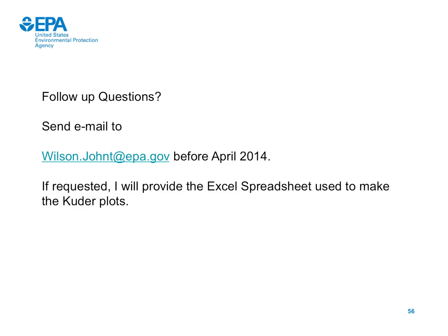Read the question to me again so I can make sure I answered it. Okay, what would be a recommended next step when CSIA shows that degradation is not occurring? All right, and so if you have a situation where natural attenuation by anaerobic biological reductive processes has not kicked in yet, it might make sense to wait. I showed you one well where cis was just starting to degrade.